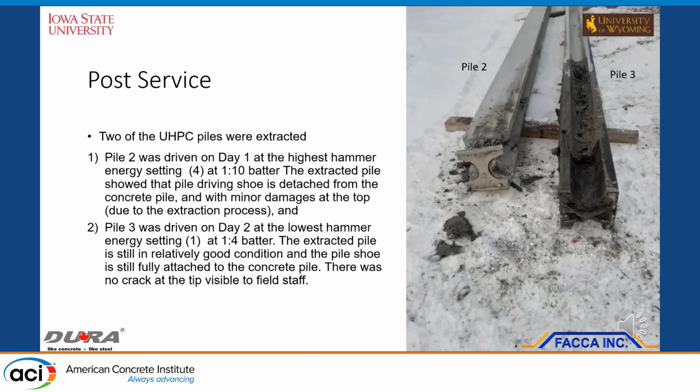Anyway, you can see on the left-hand side, pile number 2, the shoe was actually detached. We have 3 different types of driving shoes, just to test it out. The one was detached, but the rest of the piles are good. The one on the right-hand side, the shoes are still intact. So guess what? The left one, we are not going to use it again, right?